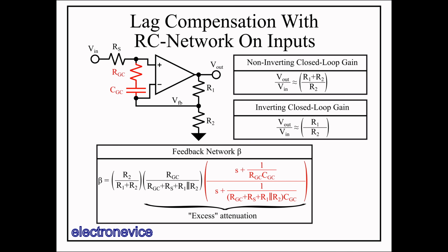Similar in structure to gain compensation, we can instead introduce a capacitor and resistor to introduce a pole-zero pair, a method called lag compensation. This effectively adds another pole to the system at low or mid frequency, which will cause a decrease in phase afterward, which is then negated by a zero that occurs at a higher frequency.